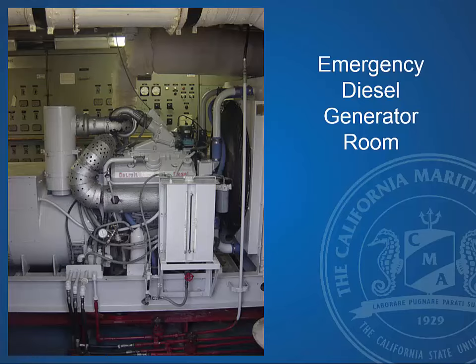Now, anytime you are directed by the chief engineer to start this generator up, one of the major things you always want to do, prior to starting it, is make sure that you have lube oil in the sump, check your radiator for cooling water, check your fuel supply. Another one that I will bring up just briefly is you have on here a trip, and this trip's an air damper. Make sure prior to trying to start it that it is not in the trip position.